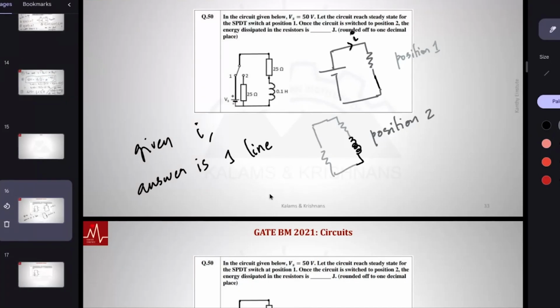Okay, I is 2. Now the initial energy stored in this inductor. Notice current cannot suddenly change; it can only change gradually. All of that energy is eventually dissipated in the resistor. What was initially stored, the initial content of the lunchbox, eventually gets slowly eaten up. So the initial energy content of the inductor is half L I squared, which eventually gets dissipated by the resistors.